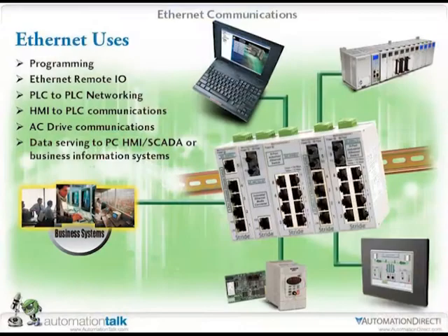Now PLC to PLC networking, you can still do serial, if you want to do RS-485 or 422. But there's some drawbacks on it, but there's also some drawbacks on the Ethernet. But what's nice with Ethernet is it's not as susceptible to noise as the serials are. Very true. Ethernet is pretty much plug and go, and Ethernet cable, I'm sure I'm going to unplug this, and something's going to flip out here, but I'm going to do it anyway.